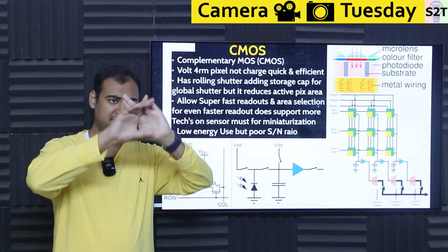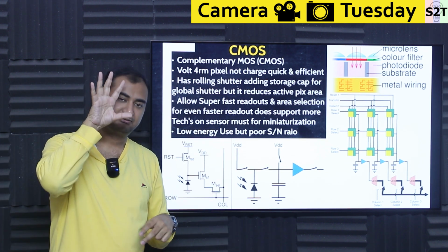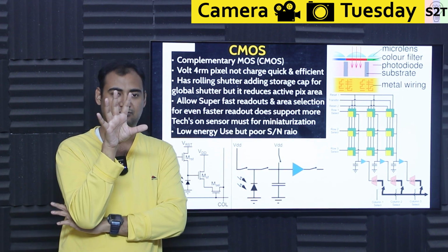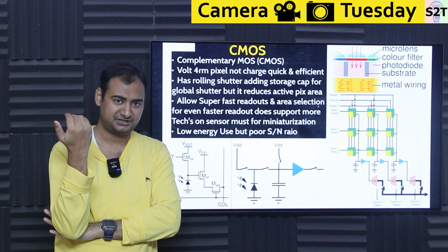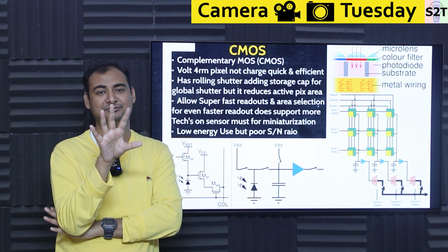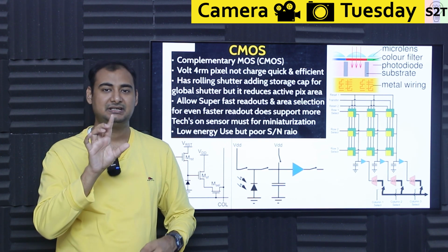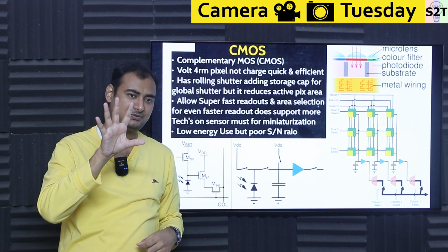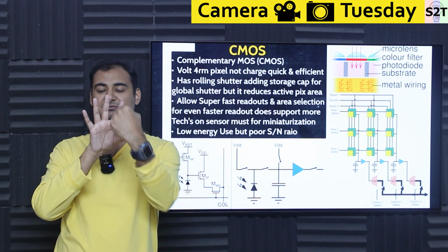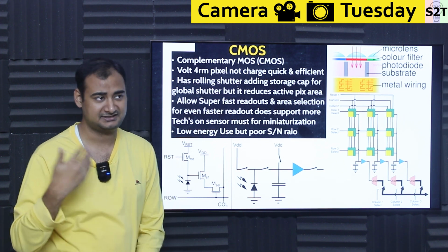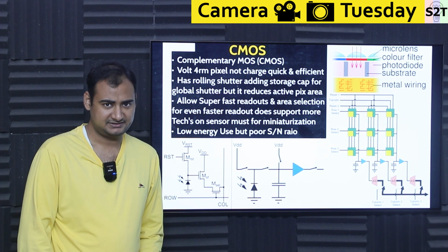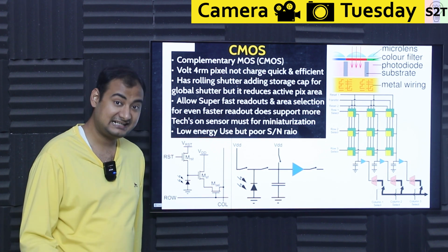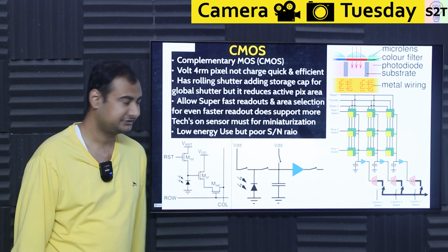Let's say you take a GoPro, you have a huge sensor. Now 4K footage inside that would be a smaller area. So what the camera will do, it will take one photo, it will read data from the gyroscope, and the gyroscope is saying you have to counter move this much in this direction. It will read only that pixel area. So in a large sensor, it can move a small box around at very high speed, as high as your FPS. So if you are running at 120 FPS, it can keep moving it 120 times electronically. So it's much more elegant, so to say.